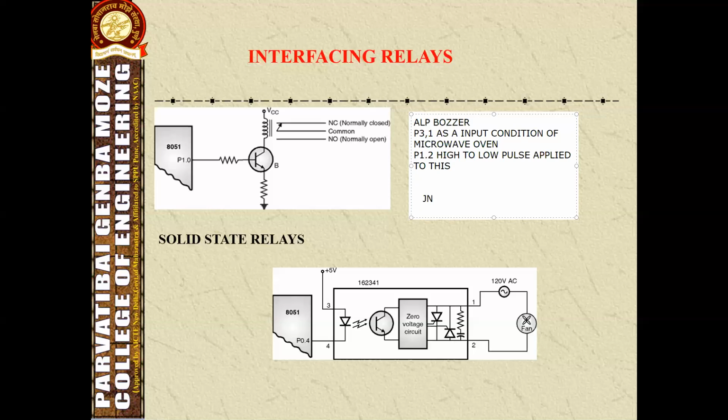First we have to jump no bit on P3.1, comma L1. Here L1 is a loop. When there is no bit available at port 3.1, it does not perform any function. It will keep itself in a loop by repeating the same step execution. If there is a bit or pulse entered into this port 3.1, then suddenly it will set the bit of port 1.2. So now this pin contains the value 1. P1.2 contains the value 1.